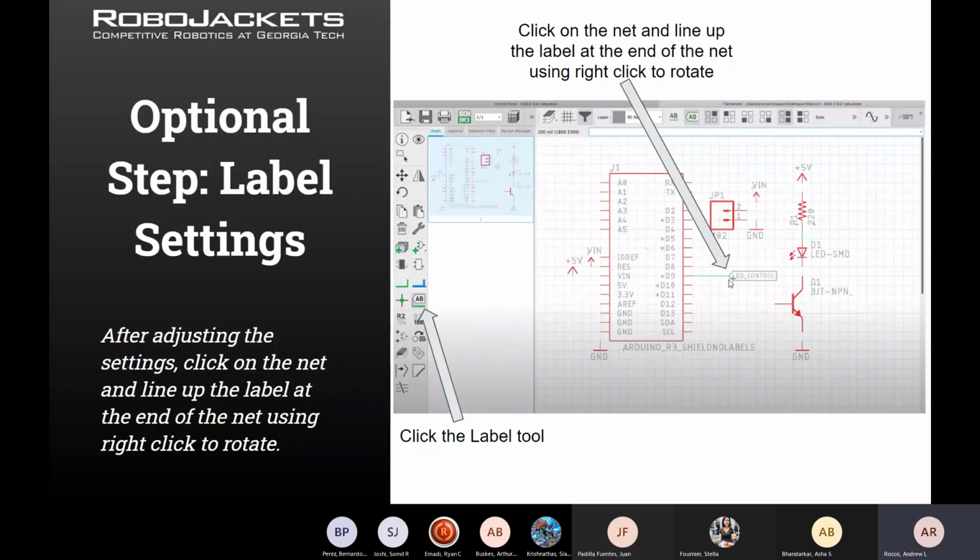So let me go back to this. Say you have another chip on the far side of the schematic, you can do the exact same thing for a certain net over there. As long as you give it the exact same name, those will be connected in Eagle. They won't be connected physically, they'll be connected through the net or the label. But when you actually do routing, which we'll talk about next week, those will be physically connected. It's just a way to keep your schematic less cluttered and looking nice, since it's not the actual physical way that the PCB will look.